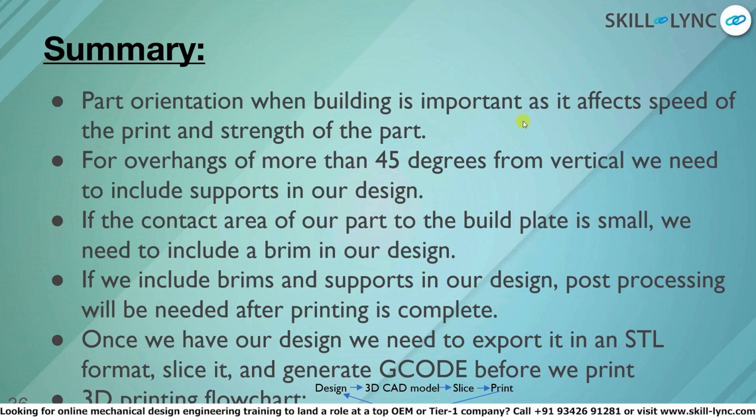If we include brims and support structures in our design, then we will need to post-process after our piece has been 3D printed in order to remove the support structures or the brims. We would also need to post-process if we used technology that intrinsically needs post-processing after printing, such as stereolithography or SLA, because that uses liquid resin, which needs to be subsequently washed off after printing.